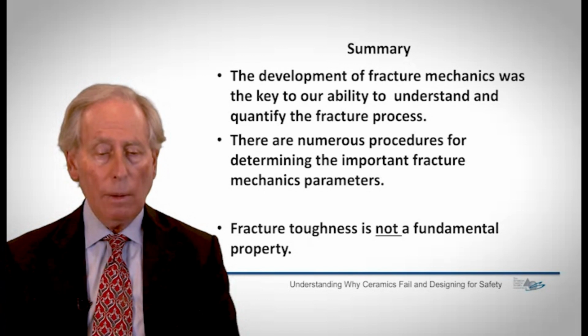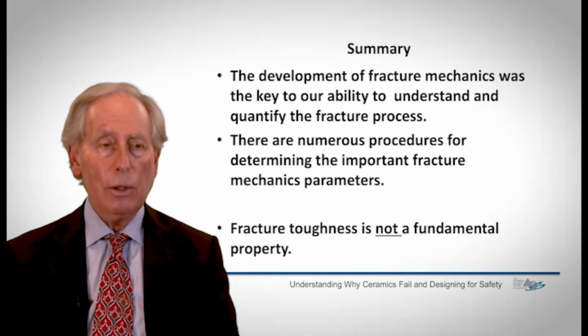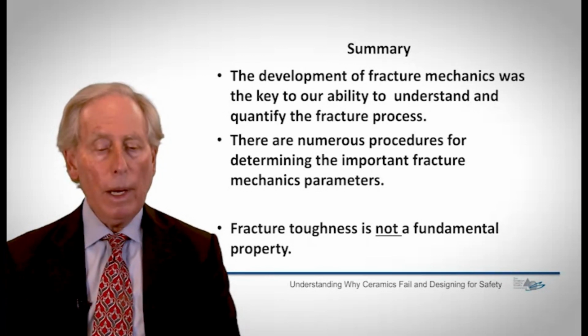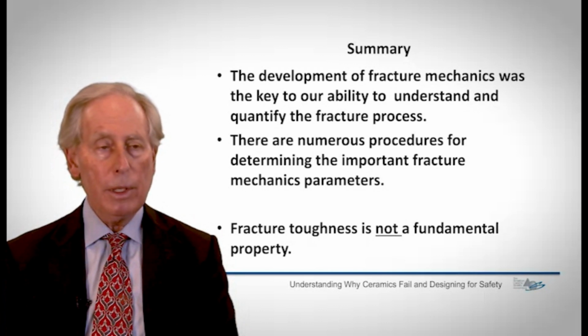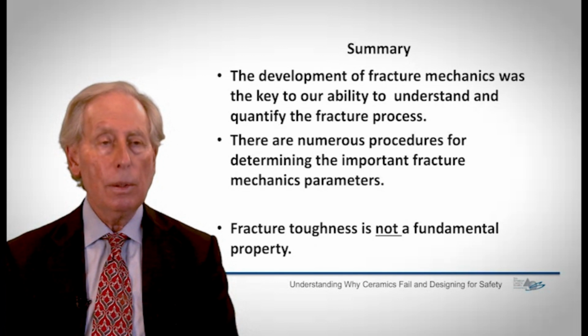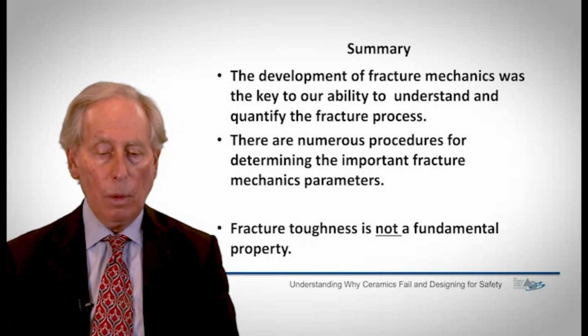I did not show all of them. There are others out there in the literature, maybe less used because of their difficulty, the complexity, and so forth. But I showed more of the common ones. I wanted to make the point that fracture toughness is not a fundamental parameter of the material. It is dependent on the particular test I use to determine it. And so one has to be careful from that point.